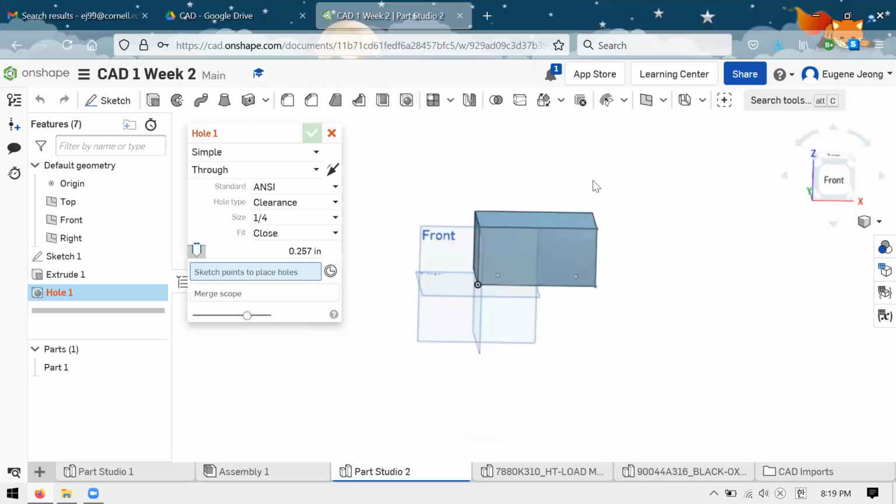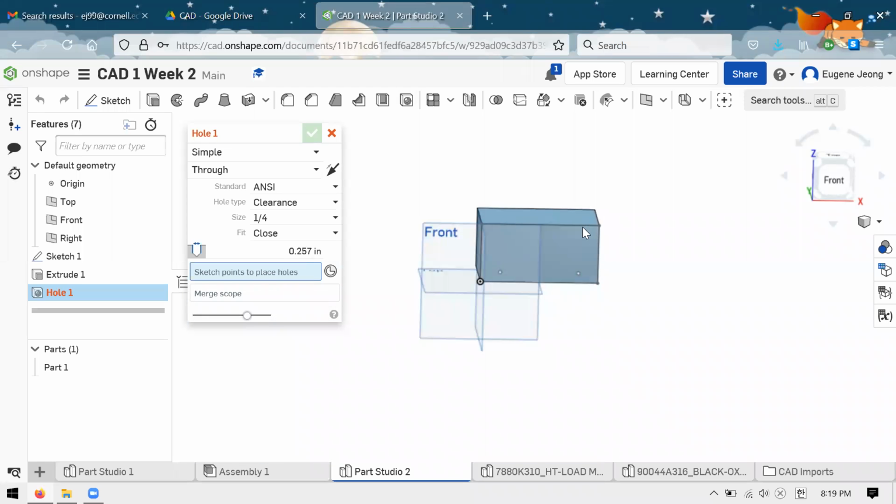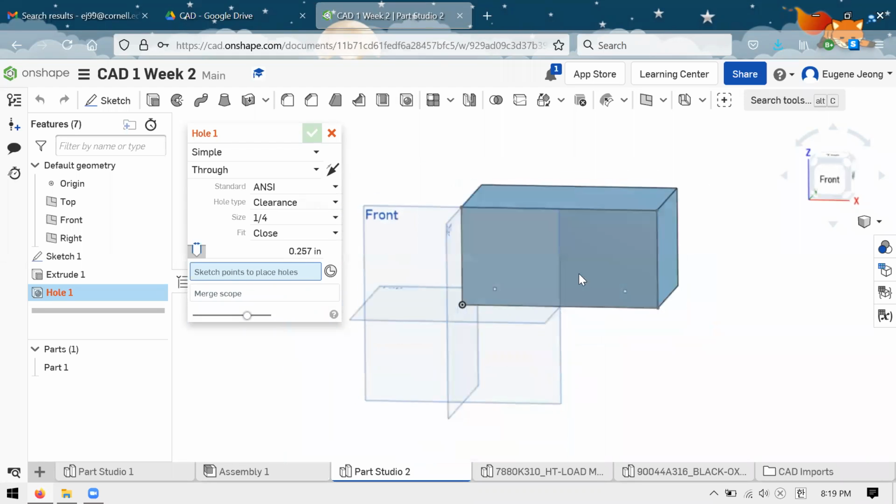You can remember last week when we made our gasket, we defined these holes in the sketch itself by drawing circles. What we're going to do now is define points where we want the center of the hole to be. And we'll use the hole tool to define the rest of the hole. Those of you who are familiar with your screw and bolt standard thread drill and tap size charts, if you're familiar with drilling and tapping, you'll know what these all mean. If you're not, don't worry about it. Just ask what kind of screw you're using and match it up.